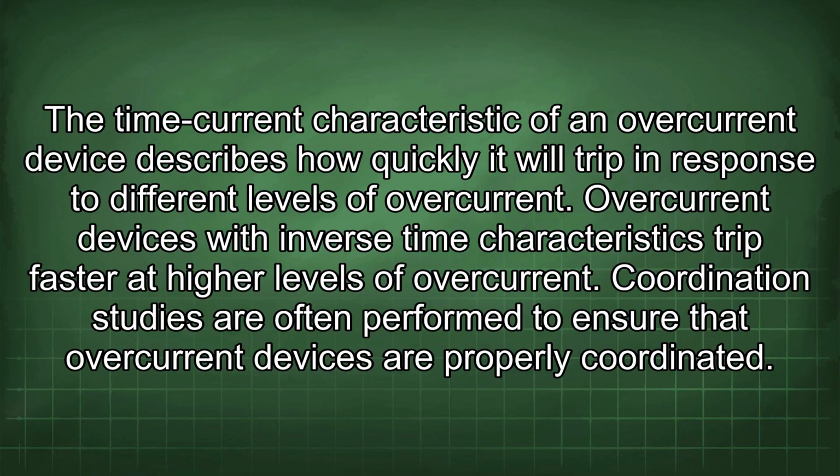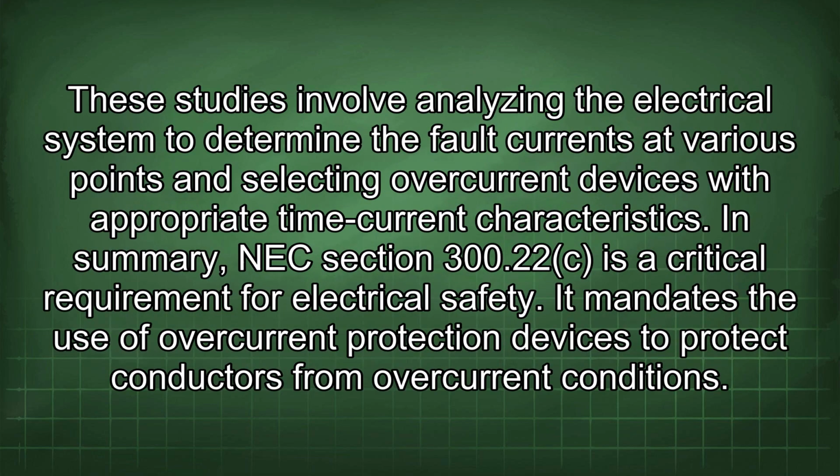Coordination studies are often performed to ensure that overcurrent devices are properly coordinated. These studies involve analyzing the electrical system to determine the fault currents at various points and selecting overcurrent devices with appropriate time current characteristics. In summary, NEC Section 300.22 is a critical requirement for electrical safety.